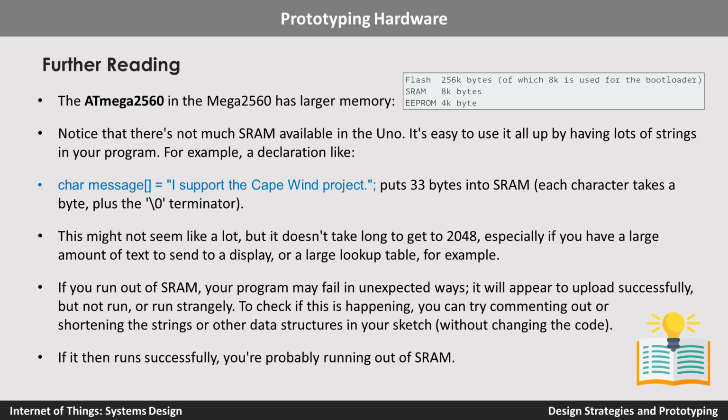However, this doesn't seem like a lot, but if you have only 2 kilobytes, then 33 bytes is a reasonable number, especially if you are looking to display large text on a display component or use a large lookup table. If you run out of SRAM, your program will fail in unexpected ways. It would sometimes be difficult to even debug to understand what is happening.